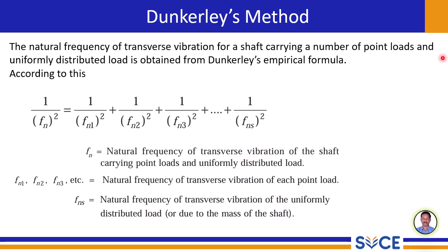This extension of Dunkerley's method highlights its versatility in handling more complex scenarios encountered in real-world engineering applications such as rotating machinery. By calculating individual natural frequencies for each load and the shaft's own mass, we can get a good approximation of the fundamental transverse vibration frequency of the entire system.